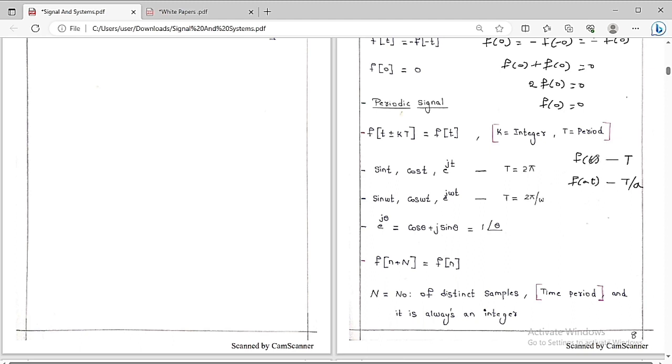So listen carefully. If f of t has time period T, then consider f of at. Here, if a is greater than 1, it is compressing the signal. If a is less than 1, it is expanding the signal. So for the time period of f of at, for the f of t signal endpoints, just divide by a, and then we get the new signal endpoints.